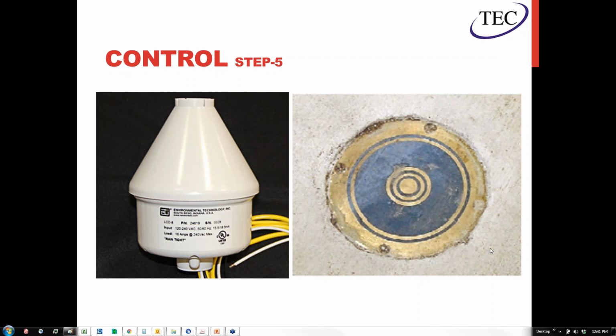The one on the right here, you may have all seen. It's like the hockey puck style, if you will, that gets mounted in the actual slab or embedded in the surface. This sensor detects the moisture directly on the surface, and it also has a sensor that measures the surrounding slab temperature, and it is used with a control that also uses a separate outdoor sensor. So the system on the right is extremely more expensive, but extremely more accurate and more interactive.